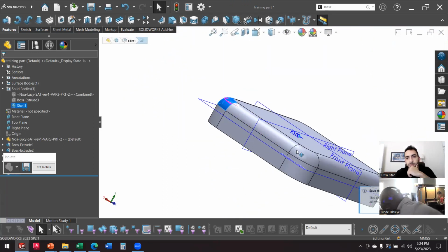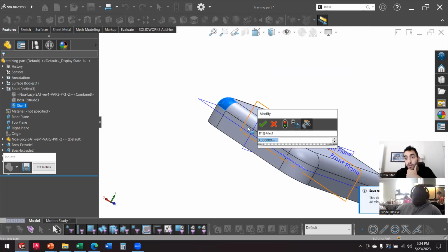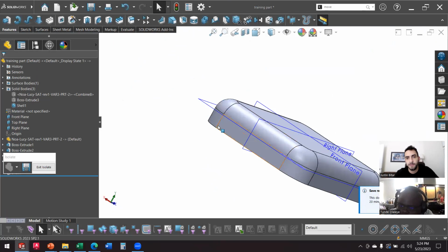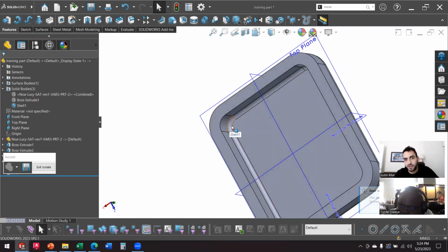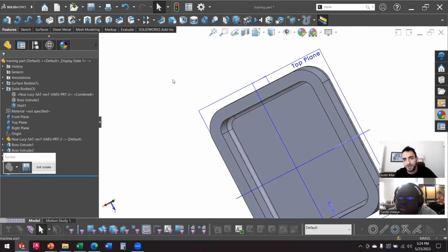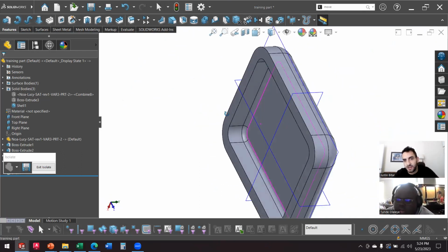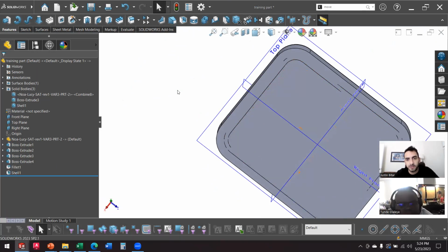And actually, if we come here and make this radius greater than the wall thickness, let's call it 4 millimeters, you'll see we'll get a corresponding interior fillet here. Okay. You don't need to worry about that. That's just something special. And then, okay, let's exit isolate.